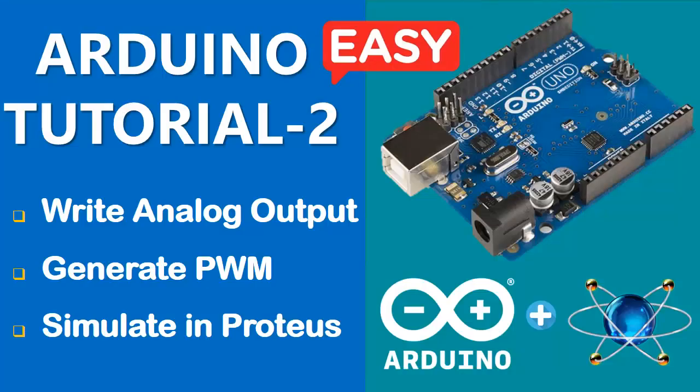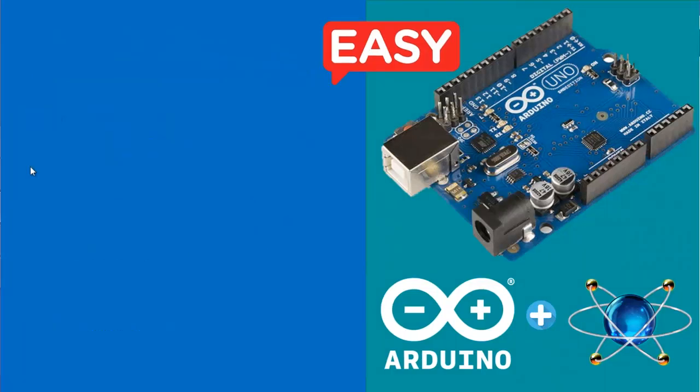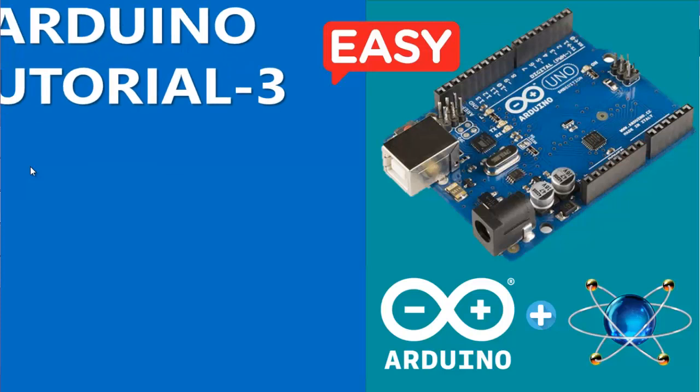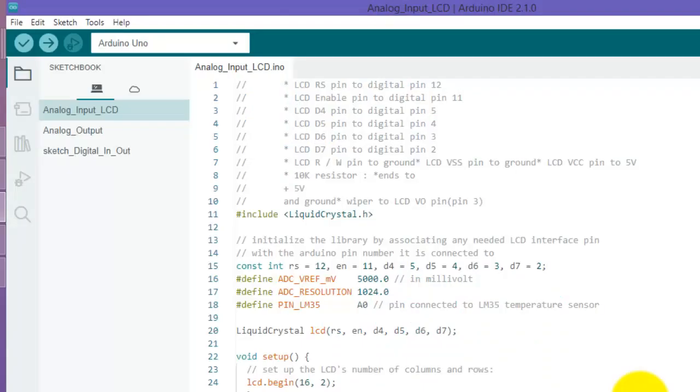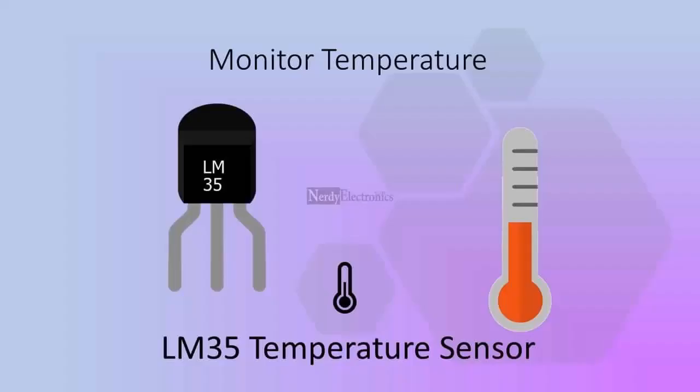In my last video, we learned how to generate analog output. In this video, we will learn how to read analog values, and this is very important because most of the sensors generate analog output. For this I am using a very common temperature sensor, the LM35. It senses the temperature and, based on that temperature, generates an output voltage.